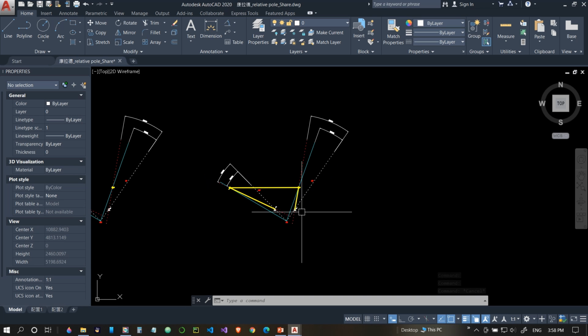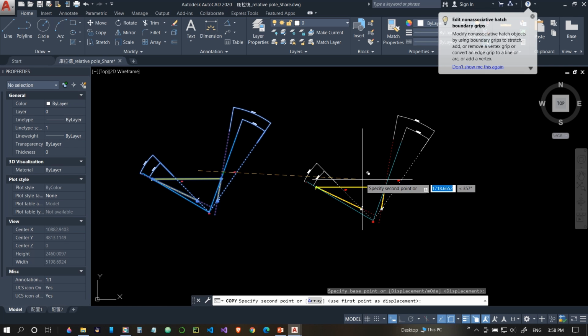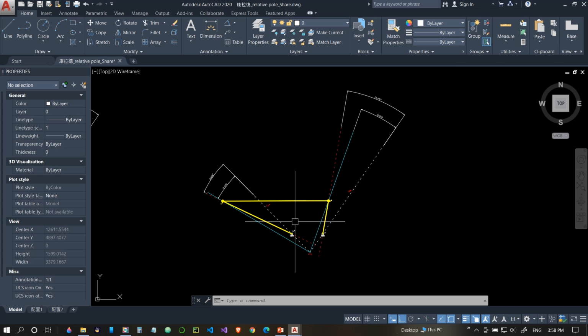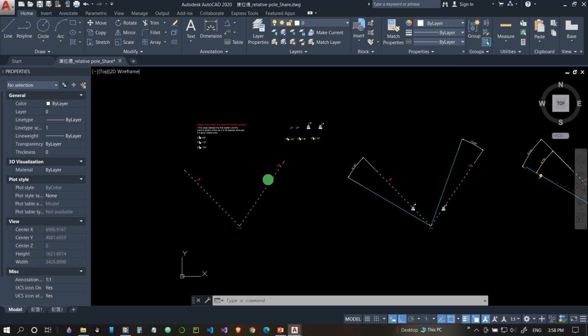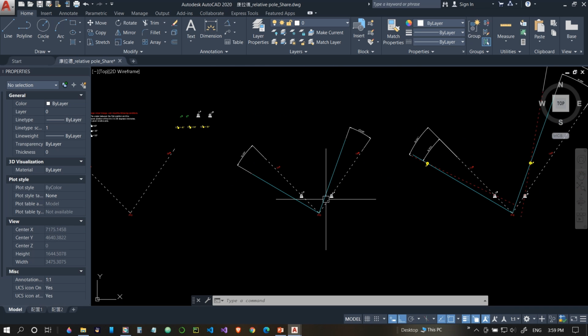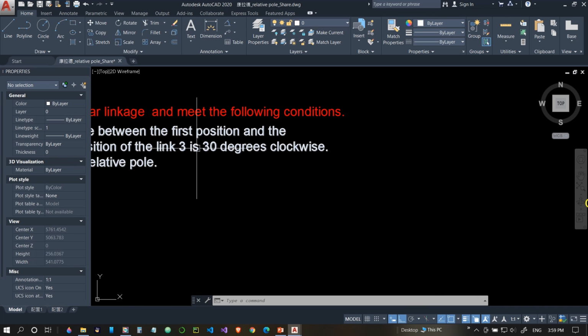And our final step, let's copy this, turn on the F8. Okay, so now that we have one step where we drew our lines at any angle, in our second step, rotate our reference line that we drew at half of what is given here.